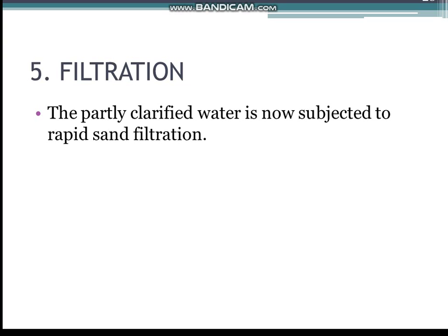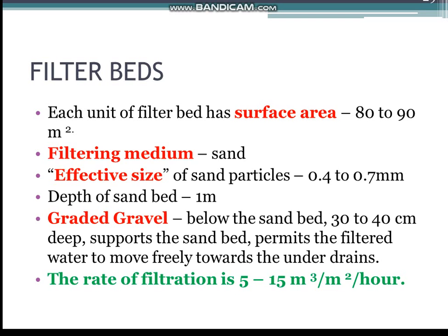For proper maintenance, the tanks should be cleaned regularly from time to time, otherwise they may become a breeding ground for mollusks and sponges. Fifth, filtration. The partly clarified water is now subjected to rapid sand filtration.